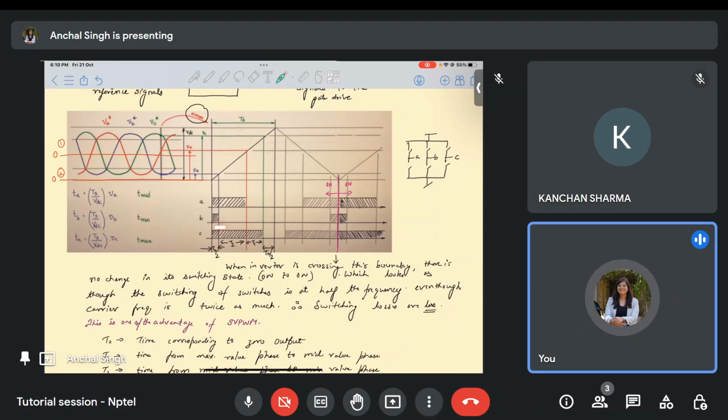This is the time period of maximum pulse width, this is the time period of minimum pulse width, and this is the time period corresponding to the medium pulse width. This was just at one instant. When you vary from one instant to another, the phases having maximum pulse width and minimum pulse width will keep on varying. So you will have to determine which is the maximum and the minimum time period at that very instant. In order to calculate that, you use these equations.